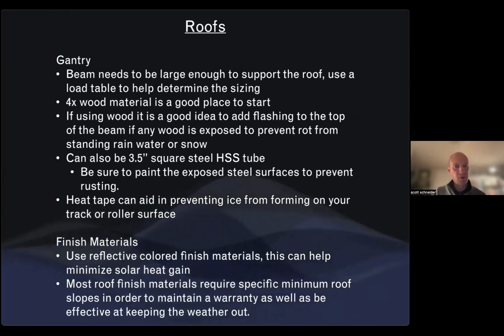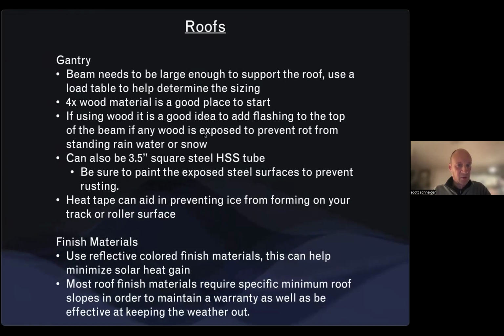And then if you're using wood, it's actually a really good idea to add flashing at the top of the wood, in case there's any kind of water that would happen to be sitting on top of the wood after it rains or something like that, to prevent rot. And it's a little bit better than painting because you don't have to keep going back every few years to repaint it.